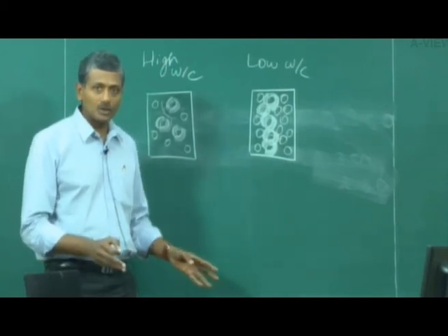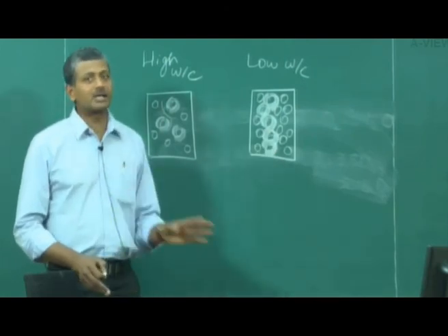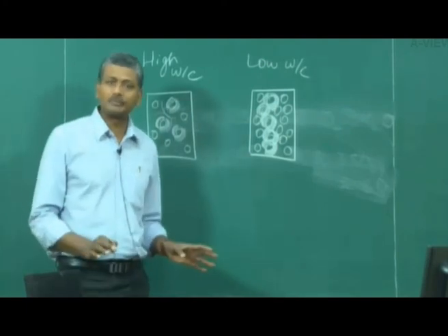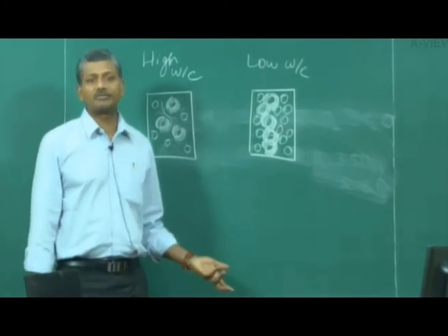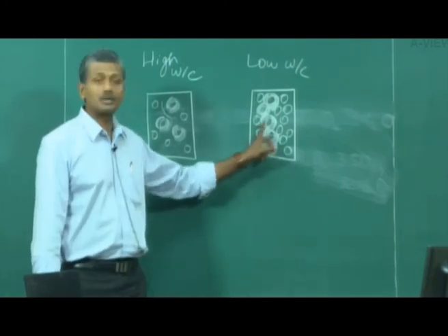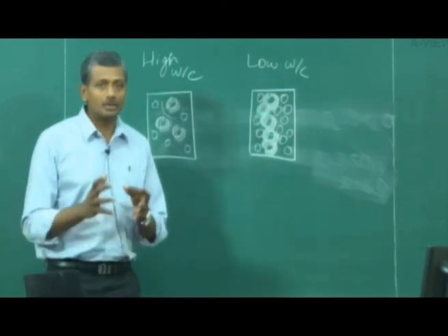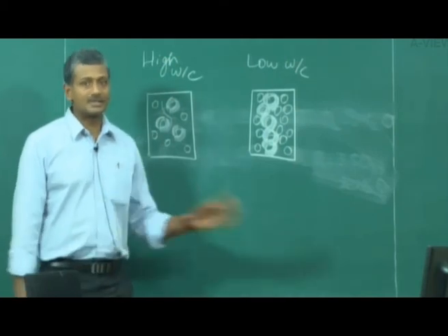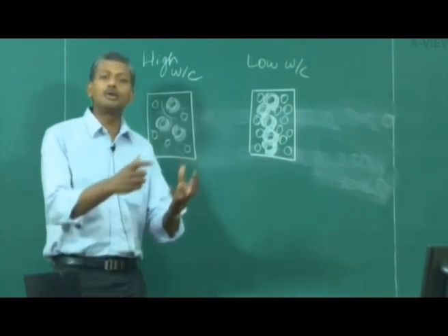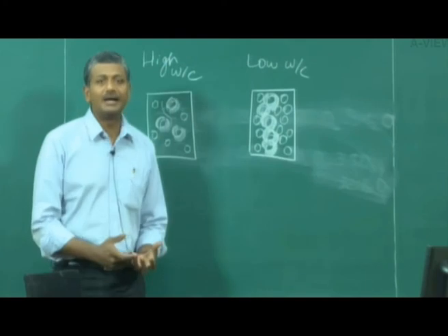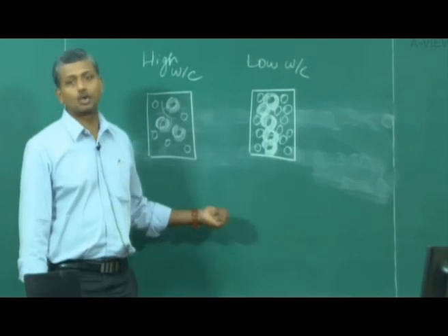Now one thing you should also understand is that when I do not have sufficient water in the system, my cement is also not going to get completely hydrated, but that is not really a problem. The remaining part of the cement which is not hydrated is simply filling up the space and working as a filler. All I need is this hydrated structure network to form, and that produces the necessary degree of binding to give me my required strength and durability. So this is a very crucial concept for you to understand, because when you have more cement particles in a given volume, you are able to create the bridges of hydration products much faster, as a result of which you get a much better rate of strength development and overall much better strength and durability in the long term.